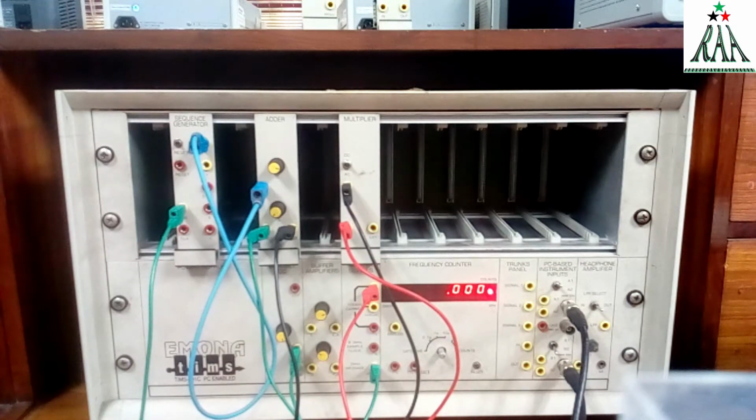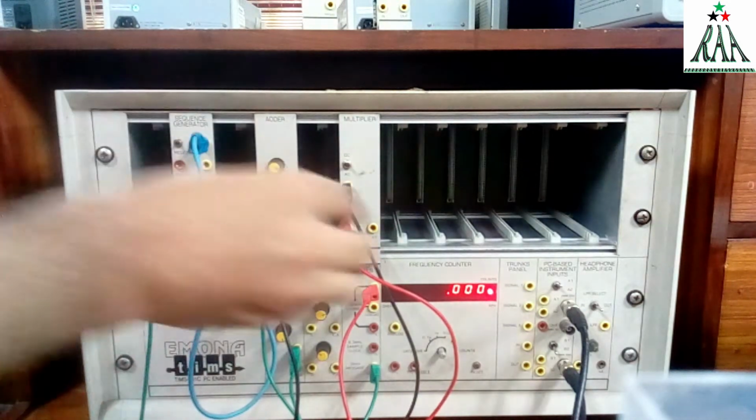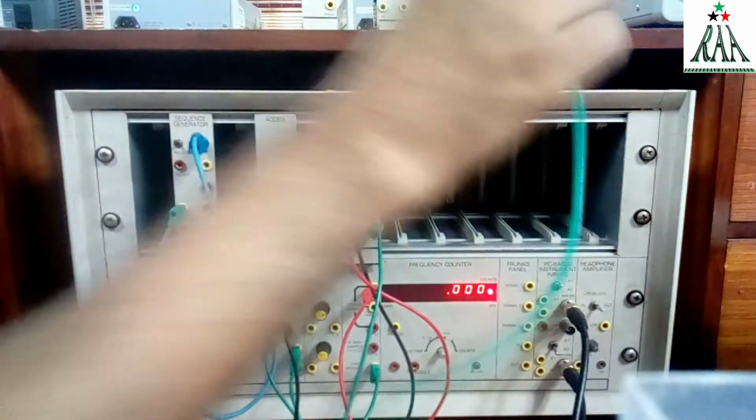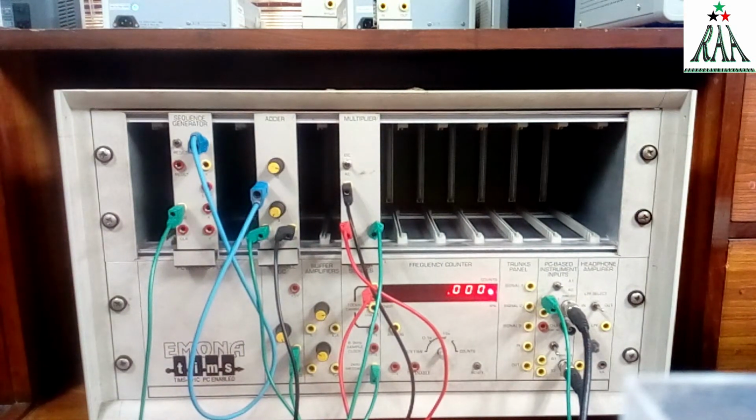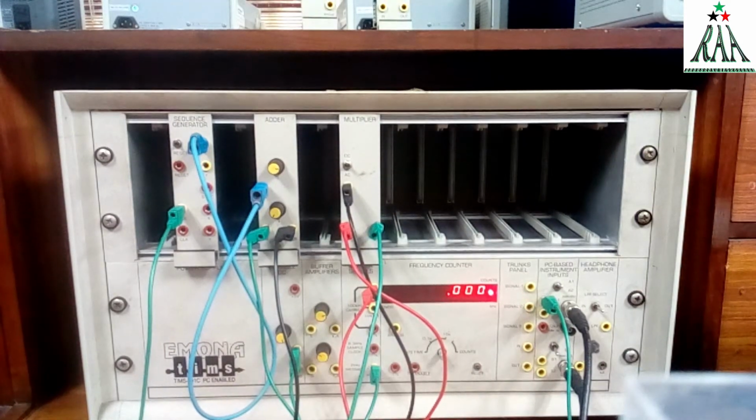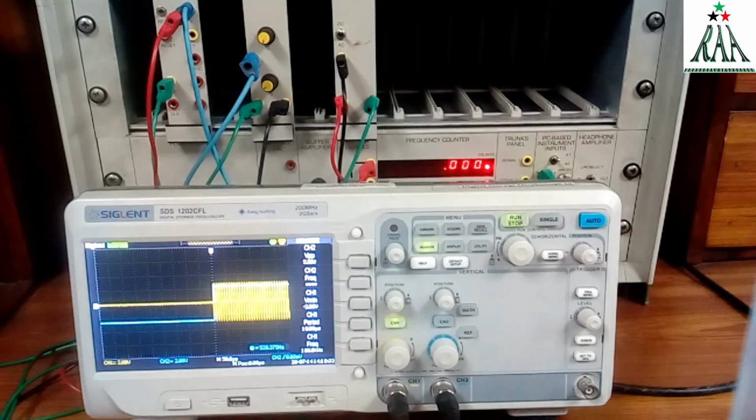Now the experiment has been set up. The output of the multiplier we will see on channel 1, port A1. After the construction of the circuit, we can see our output on the oscilloscope. The yellow one is the generated ASK wave signal, and the blue one is the input message signal, which we further converted into ASK.